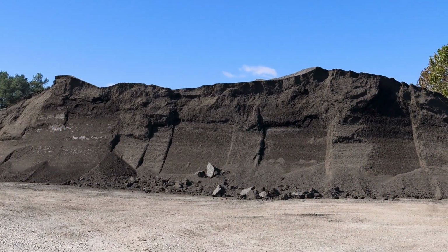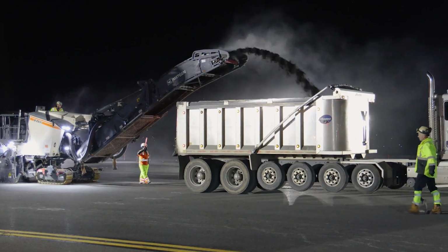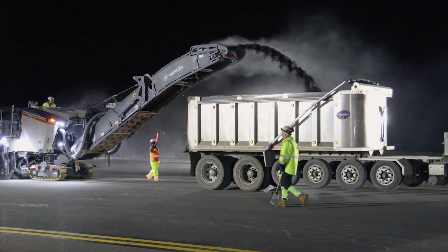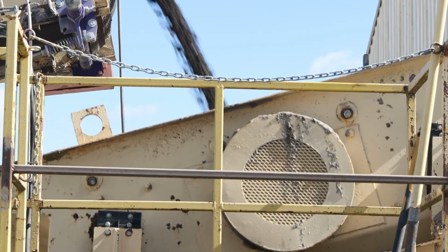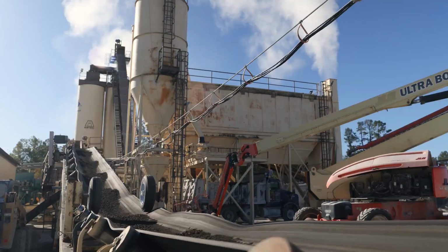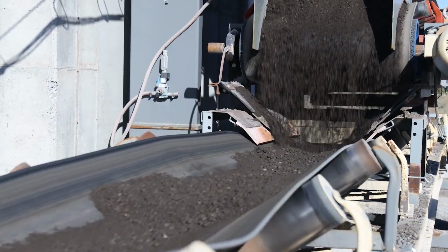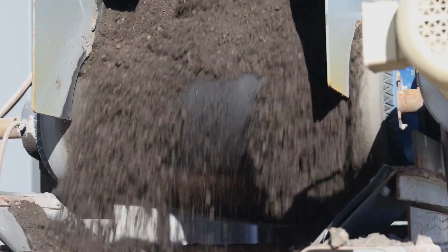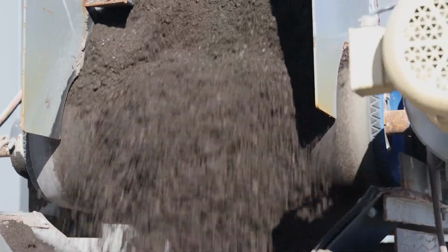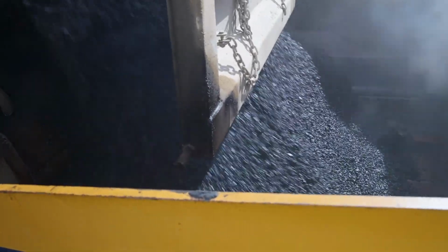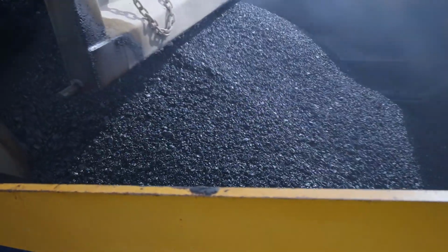Another ingredient to consider is reclaimed asphalt pavement. RAP is produced from milling or crushing existing asphalt pavement and screening it to an appropriate size. It consists of the same components as a virgin mixture and can be readily incorporated into a job mix formula. RAP is more cost-effective than other materials, helps reduce landfill waste, and aids in conserving natural resources. RAP is not allowed in the surface lift of airfield pavements except in shoulders.